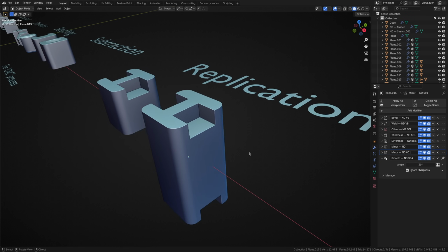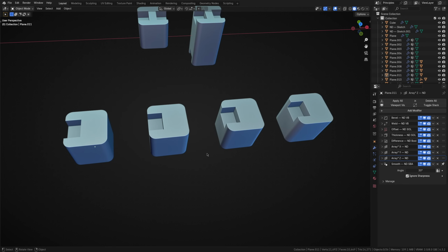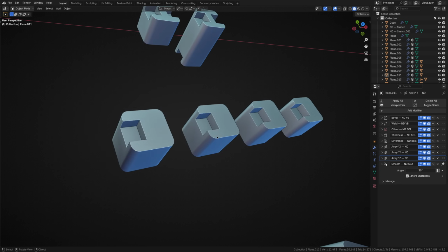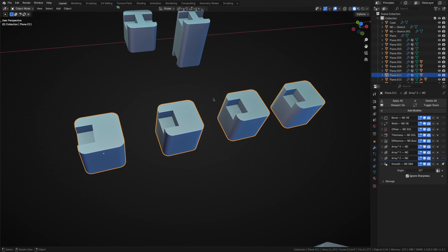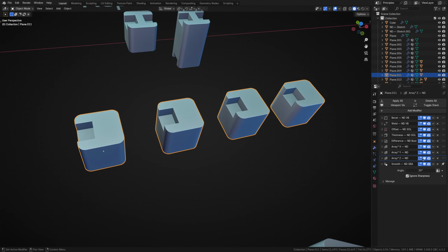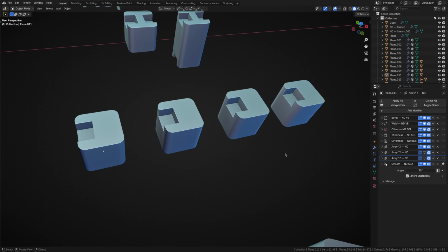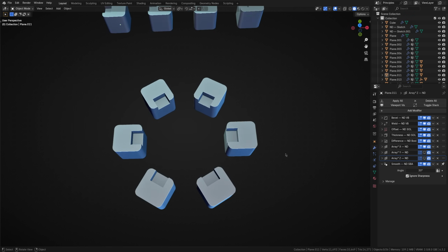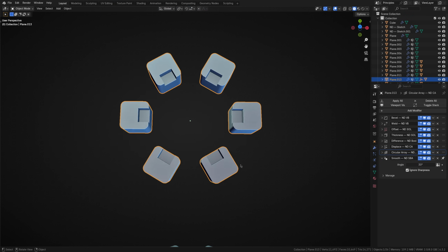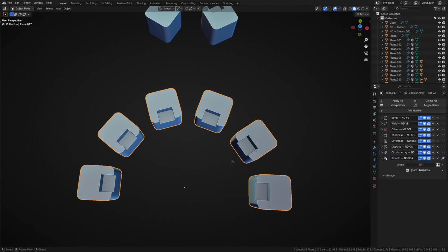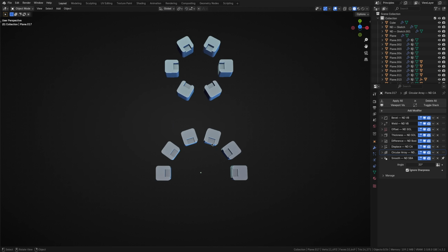Then there are other forms of replication, such as repetition. In this case, we can see an array of identical objects. There's little point in modeling each of these objects individually. Instead, we can model a single copy first and then array or instance the rest. Arrays don't always have to go in one direction. Repetition can occur in a circular fashion, over an arch, or a more freely defined path. They're just another operation to identify when deconstructing a particular detail in a reference.